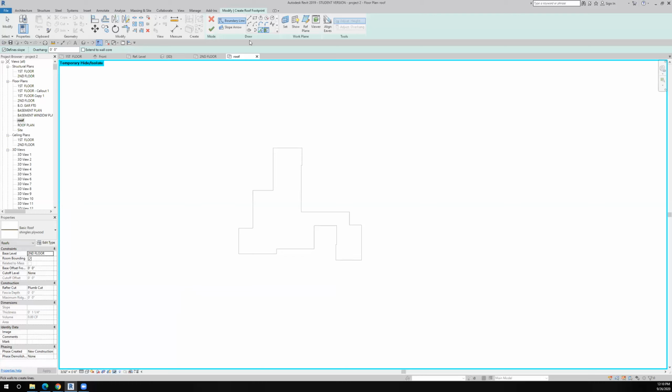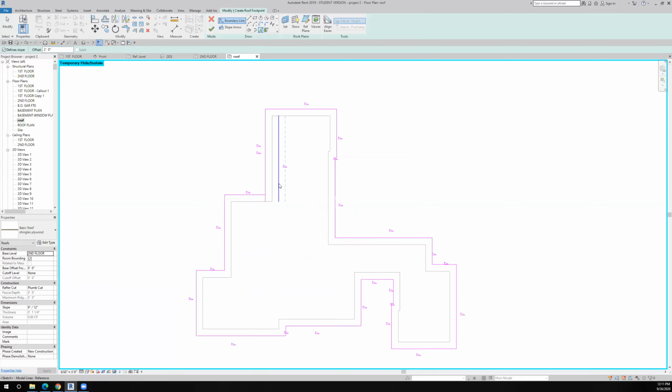I'm going to select a line and make that offset 2 feet. Then I'll come over here and double click or tab. There we go. So there it picked everything. I have some extra lines in there that I don't want, so I'm going to delete that. And it looks like there's 2 here, so I'll delete that. All right, so that's looking pretty good now.